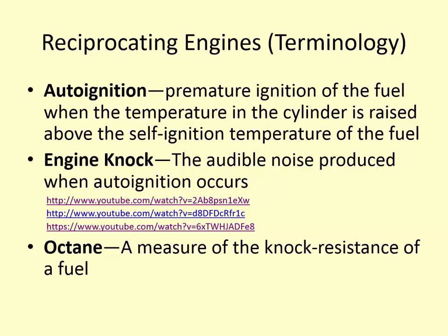And generally, high performance vehicles have a higher compression ratio, so they require a higher octane fuel because they're compressing to higher pressures, which can prematurely ignite the gas. So if you use low octane fuel in a sports car, you'll have problems with that. Another interesting thing is the compression ratio for a vehicle can sometimes change as it ages, which can cause knocking later in life for a vehicle. So if you have an old car that's knocking, you might need to give it a better fuel.